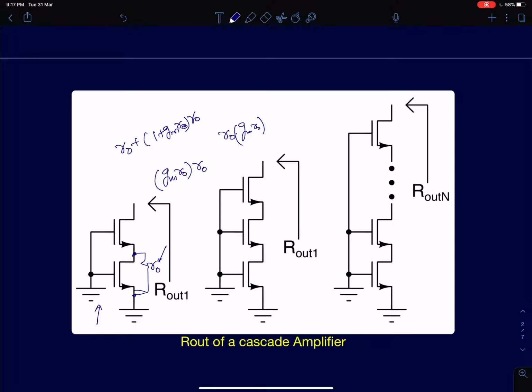Okay. Now, when should we ignore this resistance? There is also another term which is R0. So normally, if you recall from the old lectures, I discussed how you find the actual reflected impedance seen. Let's say this is Rs and you want to find the resistance seen at the drain. It's actually Rs plus 1 by Gm parallel R0, the whole thing getting multiplied by 1 plus Gm R0. So that's the actual expression. Okay. So when you see this expression here, your Rs has to be compared with 1 by Gm.